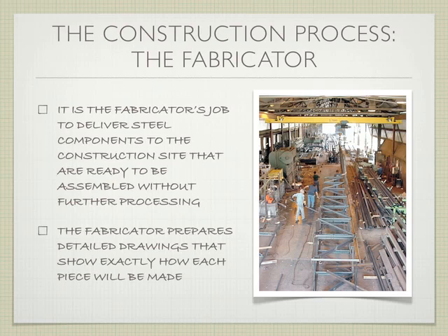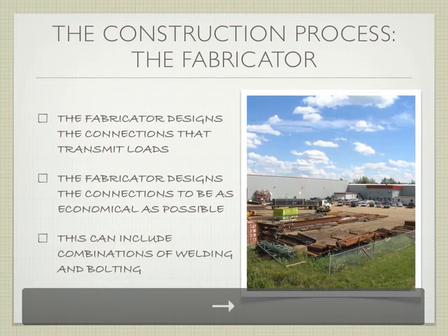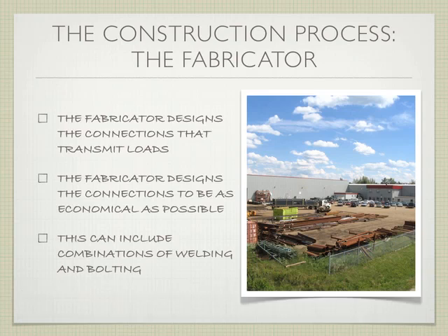So the fabricator is going to prepare a detailed set of drawings that will show exactly how and where each piece in the building should go and be used, and be connected to another piece. They're going to design all the connections that are going to transmit loads. They're going to design how those connections work. So you as an architect philosophically might say, I want this to be very open, therefore I want you to use moment connections. But you're not going to actually document how to make the moment connection. That's the job of the fabricator. So you might advise that's what you're interested in, but it's different than actually designing the connection.